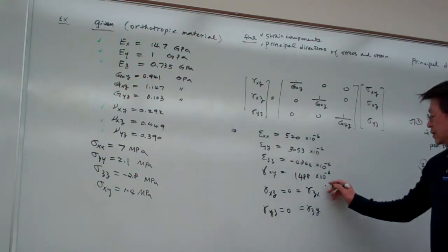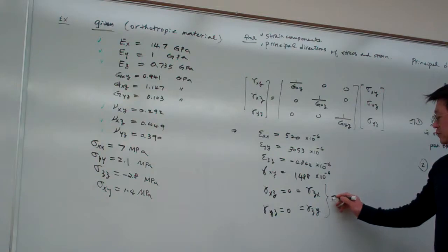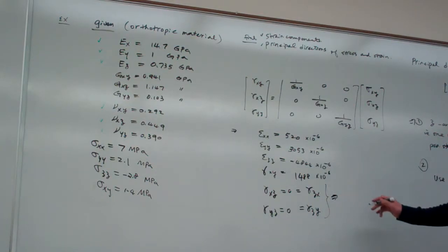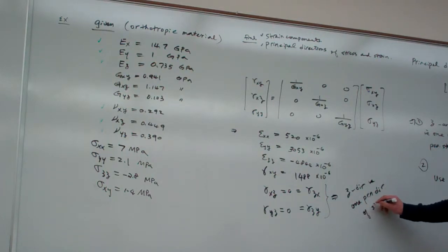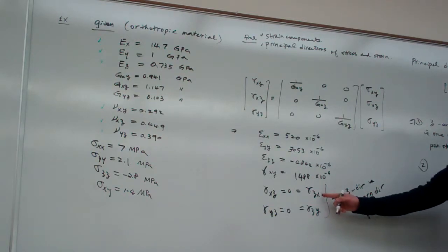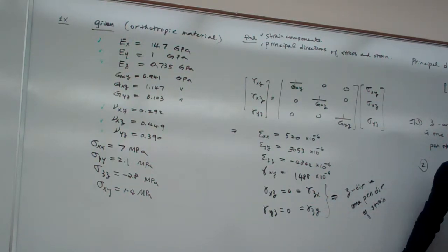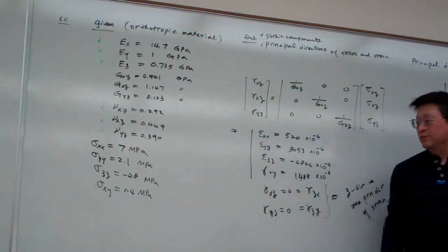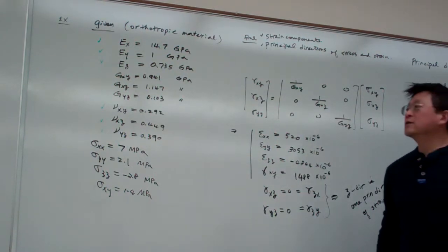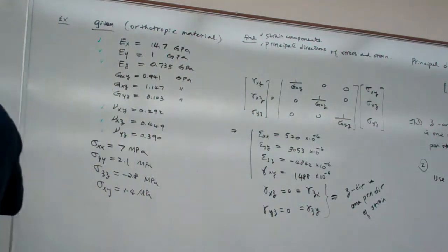The same thing, by observing this, we conclude the z direction is also one principal direction of the strain. Okay, so here we can also use Mohr circle for the plane strain condition based upon the four components here. So again, for looking for strain,